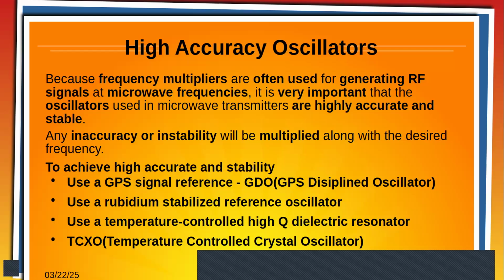And you get those in very small surface mount packages now for like 10 or 12 bucks. I don't know exactly what's in it, but it's supposed to be a temperature controlled crystal oscillator. The one I'm using is 25 megahertz, and it's accurate to much, much less than a part per million.